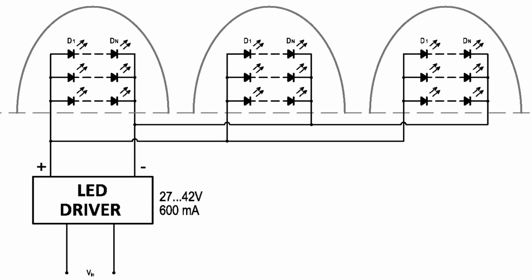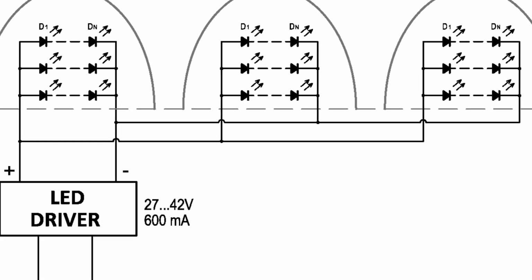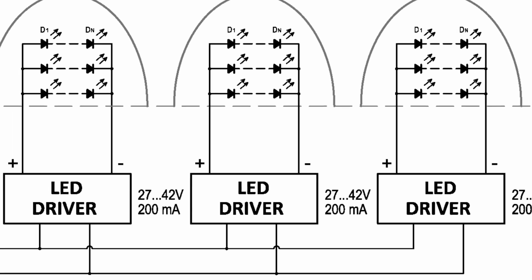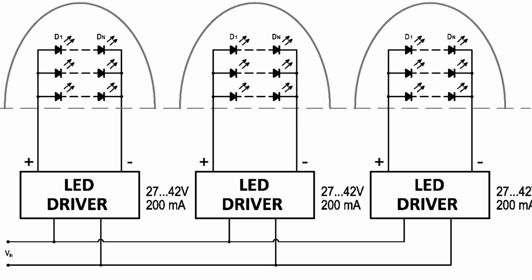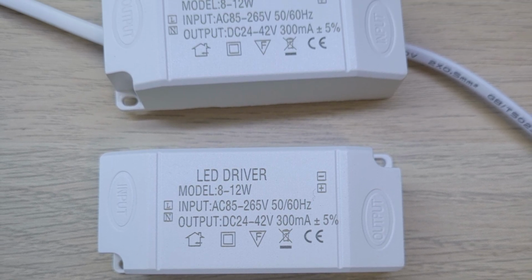This will work for us, but we will need to redesign the light fixture. It was designed and laid out with 1 driver, now let's change it to 3. It even will be more reliable. If one driver breaks, the rest will work. However, we need to change the current of the new driver.